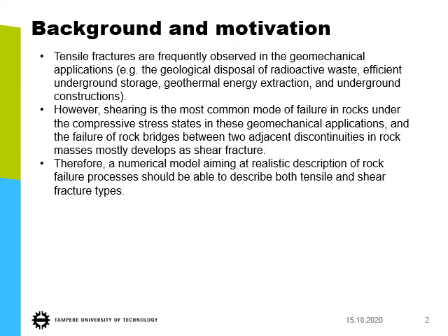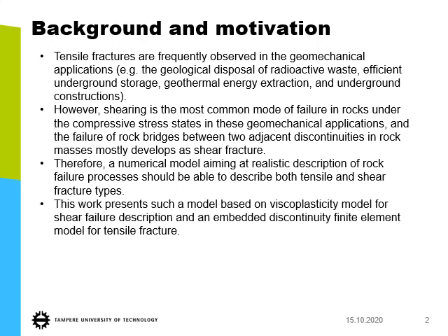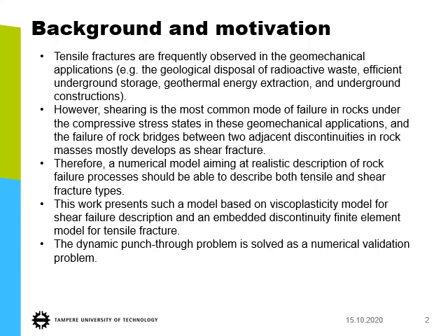For these reasons, a numerical model aiming at realistic description of rock failure processes should be able to describe both tensile and shear fracture types. So this work presents such a model based on a viscoplasticity model for shear failure description and an embedded discontinuity finite element model for tensile fracture. And the dynamic punch-through problem is solved as a numerical validation problem.